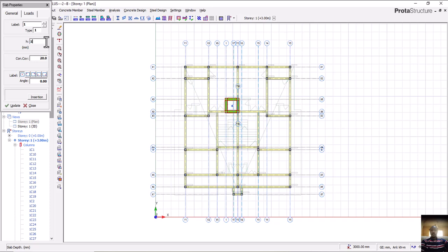Is that okay? So I'll make it 150 slab thickness, and also my cover I'm using 25, not 20. Okay, then I'll come to my load. Now this is my load. Since I already have my self weight, for this dead load at times we normally use a 1.5, isn't it? We normally use a 1.5. In this place now we have, as I said, a 1.7, isn't it?